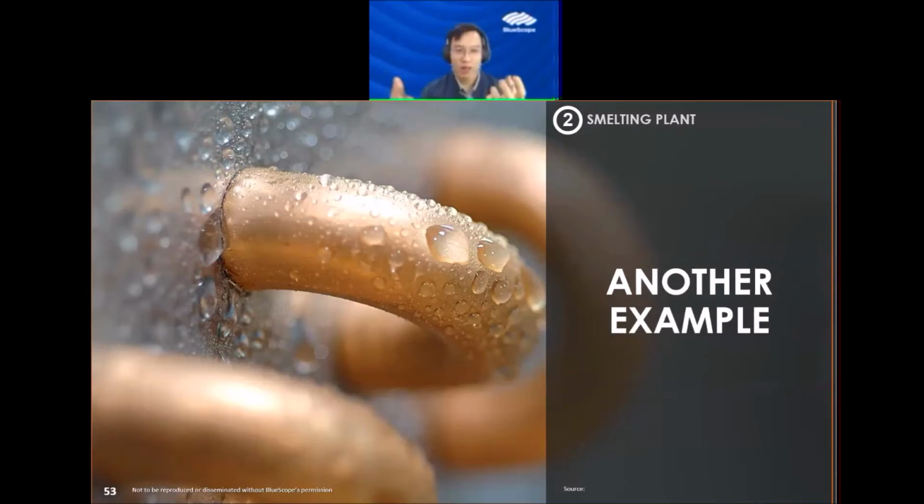And there is another example. If you have seen a heat exchanger or so-called air conditioner fins, sometimes you see droplets coming out from there. This is also because the fins themselves are cold, right? The pipes are cold, because of the coolant, because of the cold liquid inside. And the outside air is hotter, so it will start condensing onto the surface.